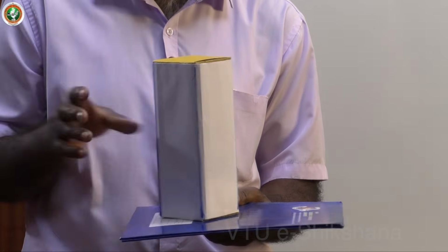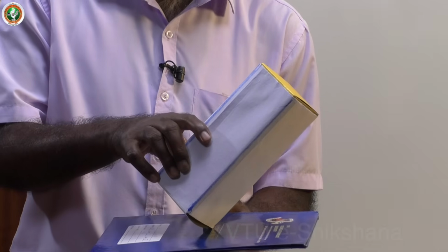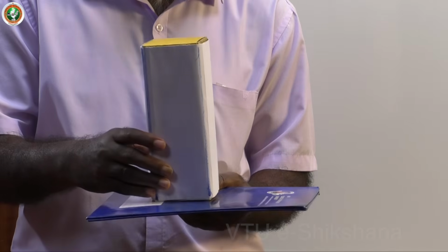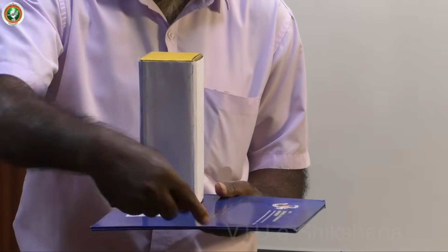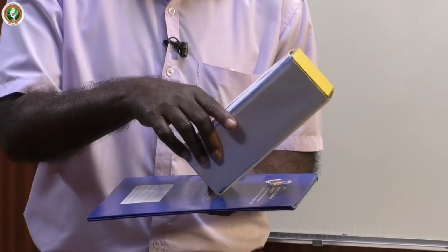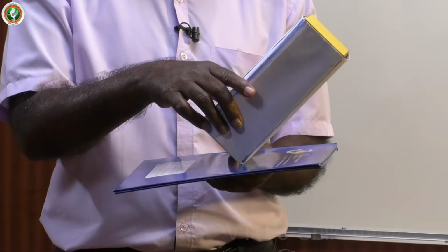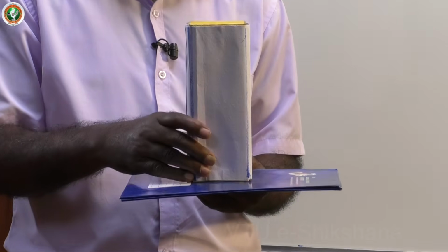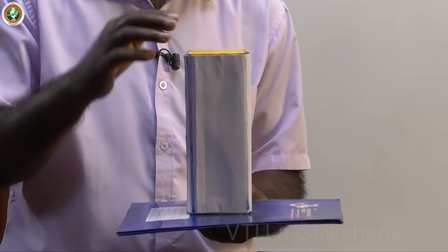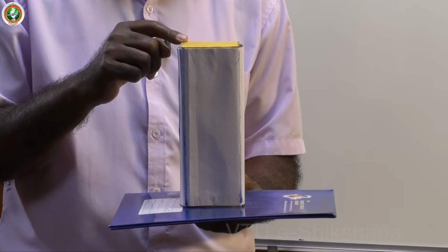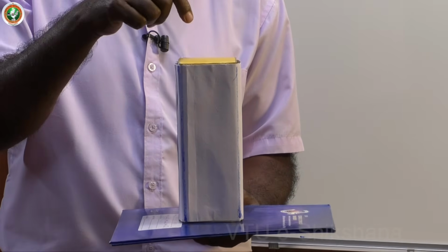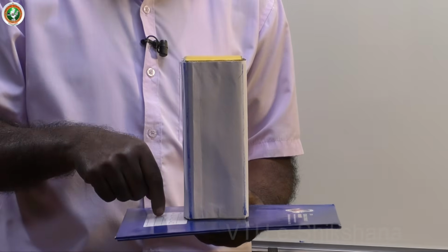Suppose that I keep it like this at random. Then rotate, then it becomes a corner. So necessarily you must assume that there is a line perpendicular to it. I'll keep like this and then rotate. So this is how you must identify. Now the axis is inclined at some degree to HP. So what you should do is make it perpendicular to HP so that you get the true shape on HP. So once the true shape is on HP, the top view is the true shape.